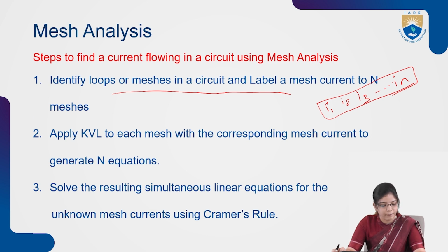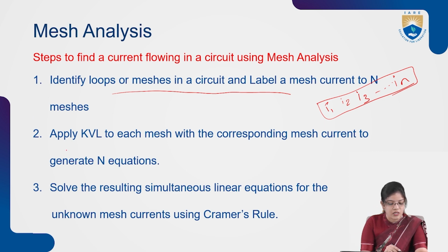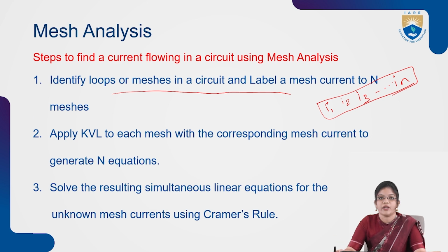The second step is to apply KVL to each mesh with the corresponding mesh current to generate n equations. So we apply KVL in each mesh and find out the currents.